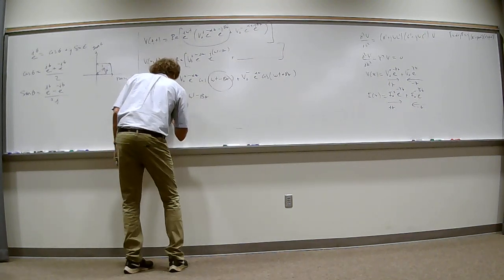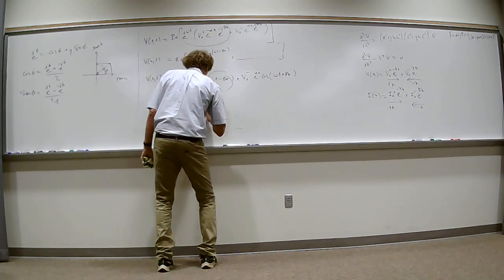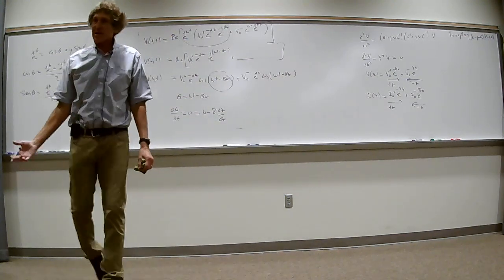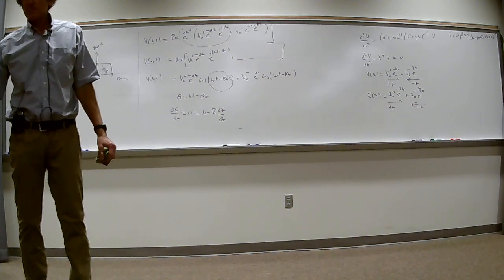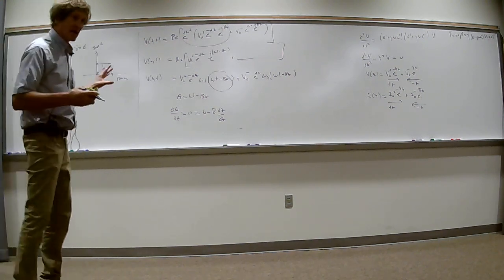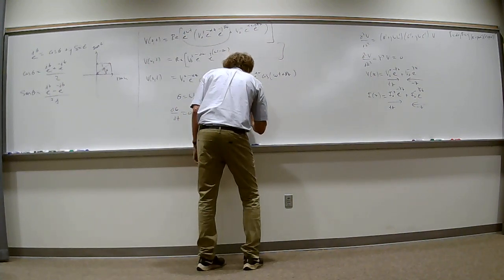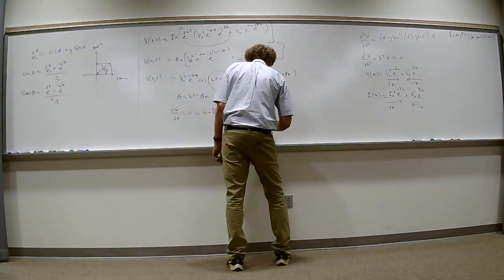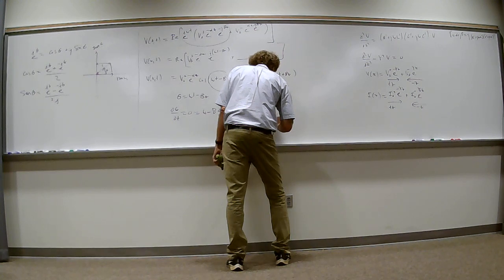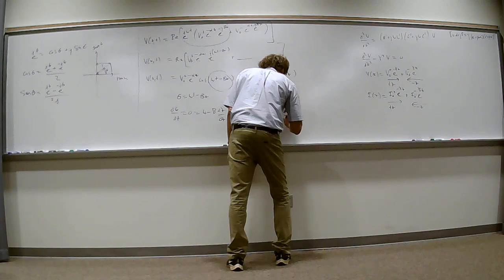We take a derivative of this with respect to t, we set it equal to 0, and we get simply omega minus beta times dz/dt. Now dz/dt is just like dx/dt, it is a velocity. Y'all follow me on this, class? That's called the phase velocity because we're tracking the phase of the wave, or the angle of the wave, how fast the constant angle moves. From here, you can see that we get phase velocity equal to, and just take the omega to the other side, it's minus omega, then divided by beta, and that's equal to omega over beta, and that is dz/dt.